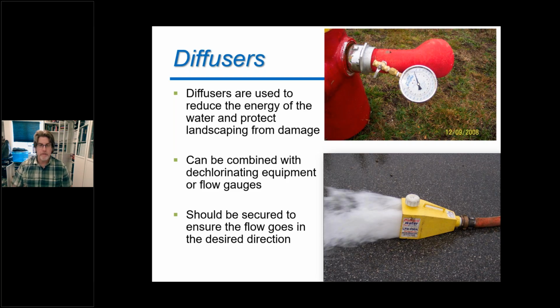Whether you're measuring flow or dechlorinating with your diffuser, no matter which type of diffuser you use, make sure it is secure. You are going to be expelling large volumes of water, and there's going to be lots of energy being expelled from that blow off or from that hydrant. You want to make sure that these are secure, and this picture at the bottom with this diffuser just kind